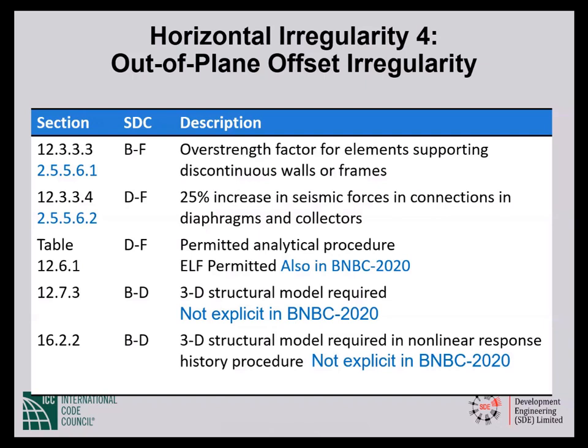Permitted analytical procedures. ASCE 7-05 will permit equivalent lateral force procedures, so will BNBC 2020. 3D structural model required by ASCE 7-05. That is not explicit in BNBC 2020, but it should be very much encouraged.